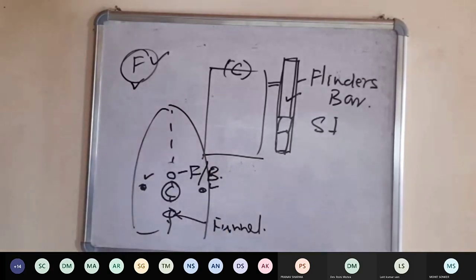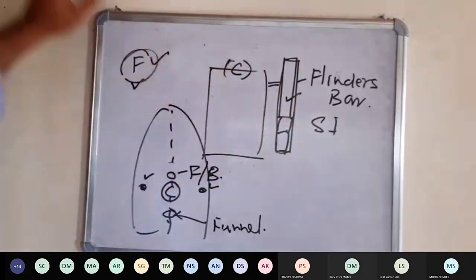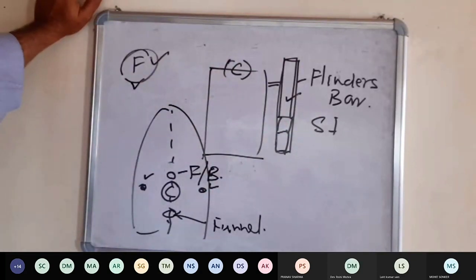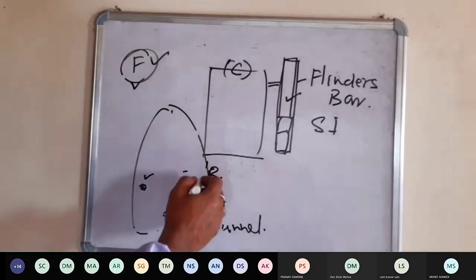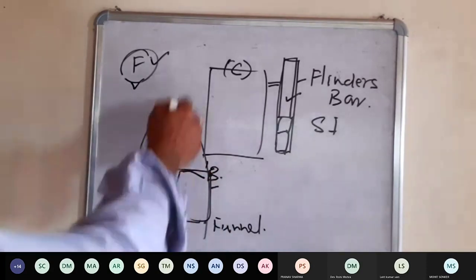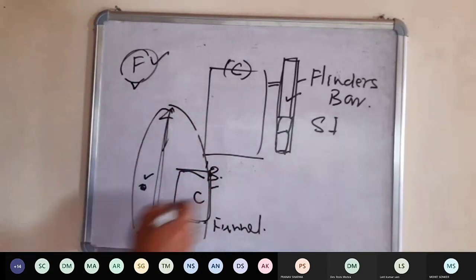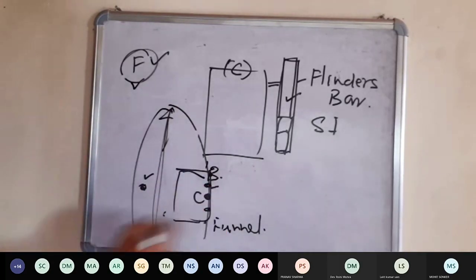The Flinders bar is probably named after a captain who found out this problem and solution to this, that by placing a rod like this, we can nullify some of the effect of the vertical rods. And so in his name, it is called Flinders bar. Just for an idea, if the ship is, let us say, an aircraft carrier, the accommodation will be here for the runway to be free. The compass can be offset. Here it can be very close to some pillars on this side.